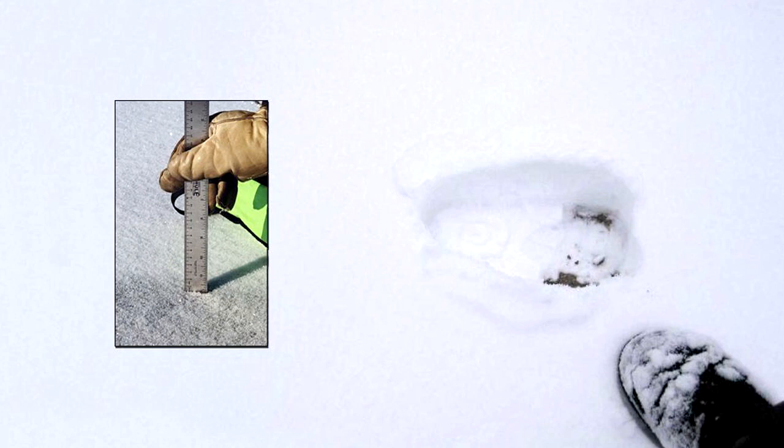The recommendation by the United Kingdom CAA is that takeoff should not be attempted when the depth of water, wet snow, or slush is more than 15 millimeters. But check with the aeroplane flight manual in case it has a more severe restriction. The information on the contamination will be provided by the aerodrome and issued to the pilot through a report. These reports are either by SNOWTAM or a runway state code. Use these reports and your aeroplane flight manual to best gauge the performance considerations.